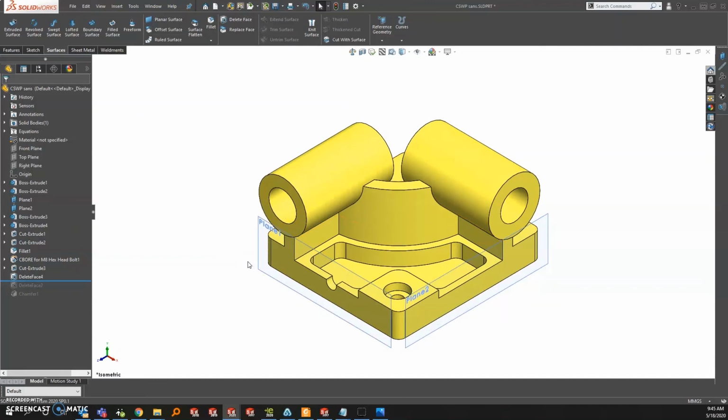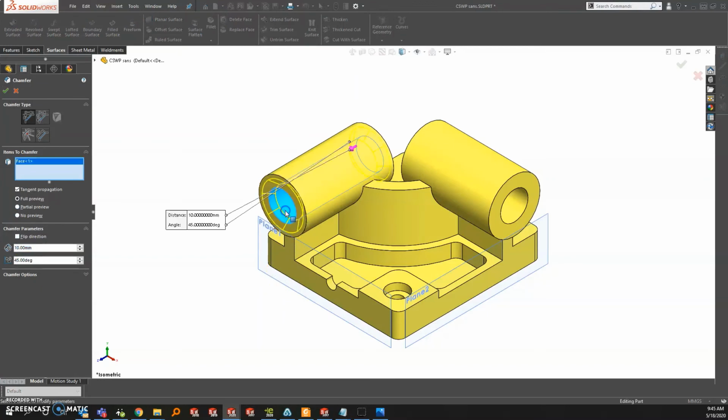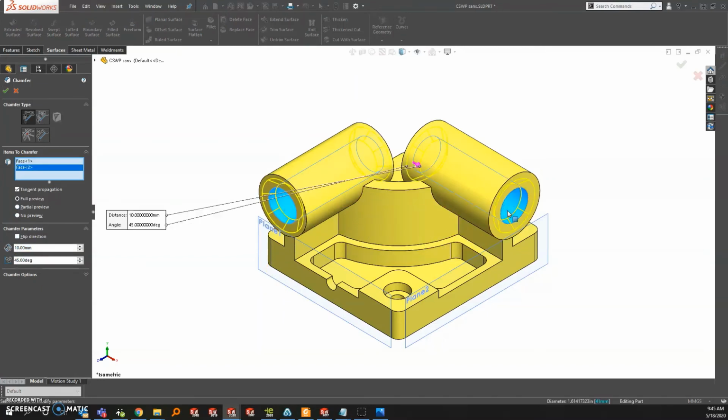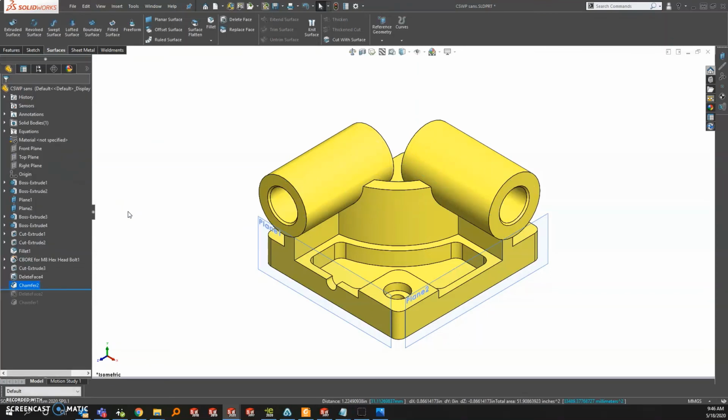So now let's add a chamfer. We can go into here because I have that set to my sketch tools. We'll add this chamfer right here, and let's just make 2 clicks on those faces. But our chamfer shouldn't be 10 millimeters. It should actually be 2 millimeters for this project. So right here, instead of going the whole way back to the property manager, we're just going to click there, hit 2, hit enter, enter again, and now we've created our chamfer.